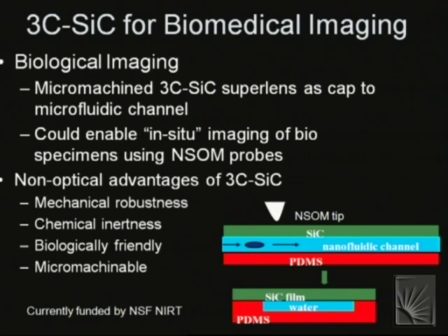We are actually building a simple microfluidic system that consists of a substrate that has machined into it somehow, or printed into it somehow, fluidic channels that will serve to deliver biological specimens. We claim that we would be able to position the biological specimens within close proximity to the NSOM tip and utilize that lambda over 20 capability that inherently exists with the NSOM structure to image the biological specimen in its natural state, because the super lens allows you to extend the depth of field.